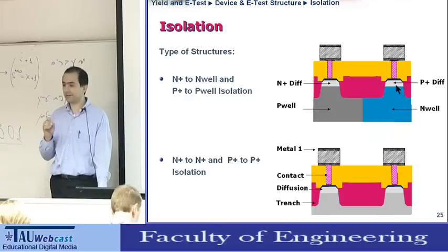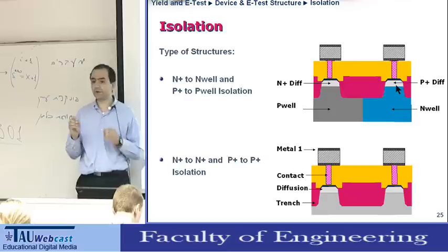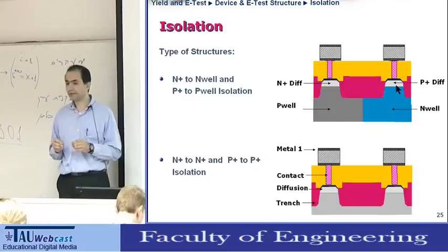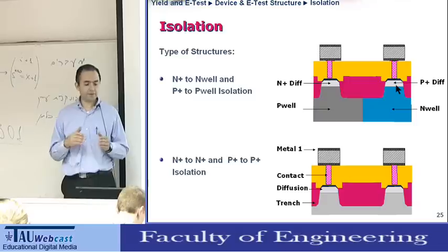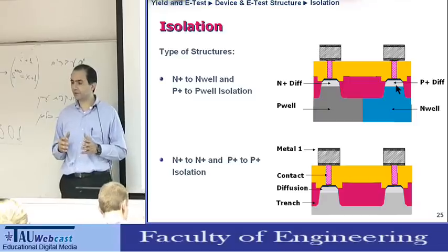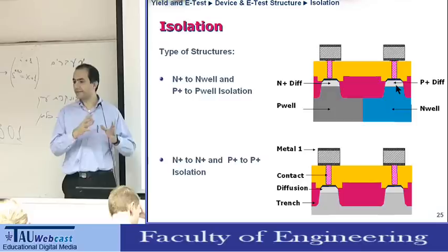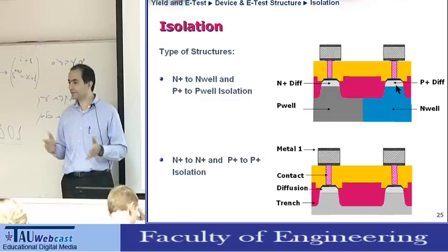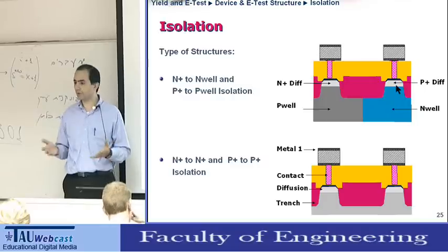Something happened on this wafer. Either the trench is not in the right thickness or the doping is not the right doping. And this means that even if the breakdown voltage is 4 volts, there's a problem. And in some other areas, it might be smaller. There's a lot of variation, so it might get smaller, and we decide to throw this wafer away.